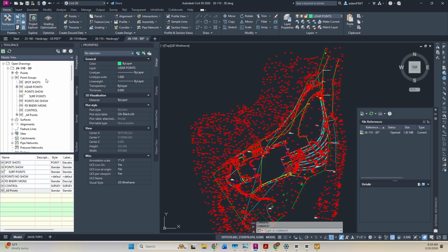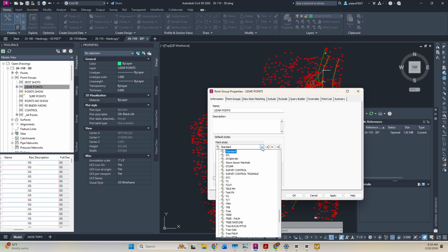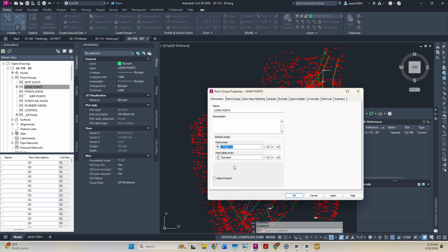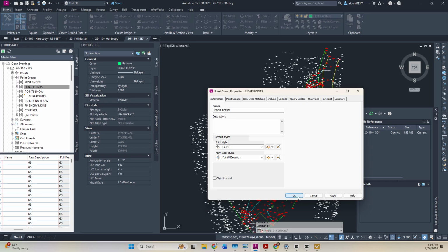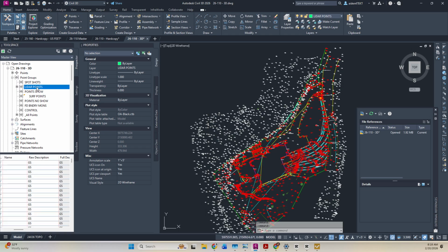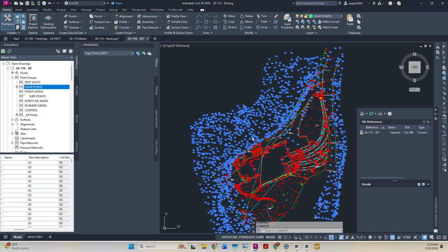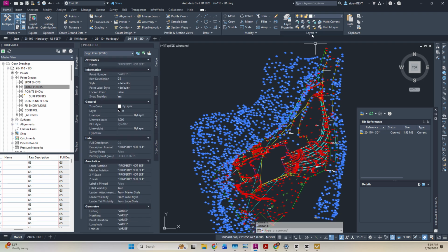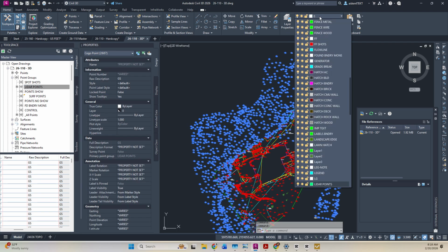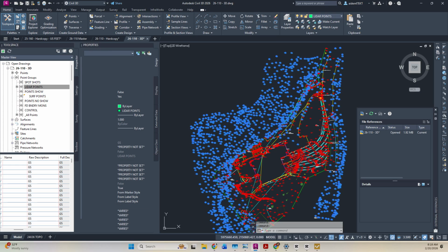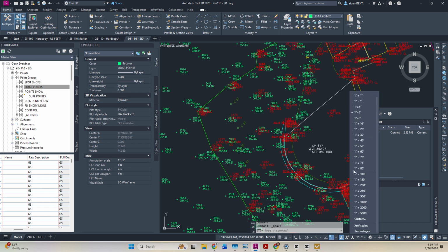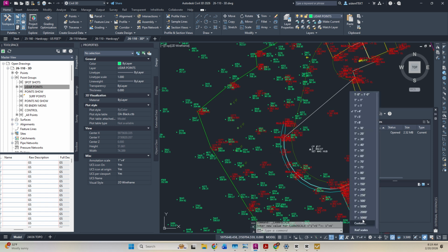All right. And then your LiDAR points, properties, points X. You can give it an existing point 1, and then point number and elevation. That's what we really care about this one. So you gotta select all these. Careful when you select a lot of COGO points in Civil. If you don't have a good graphics processor, that could take you a while. Okay. Let's change the scaling from 1 to 4 back to 1 to 1 again.